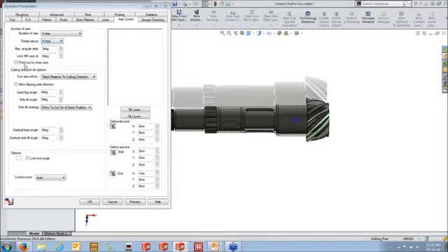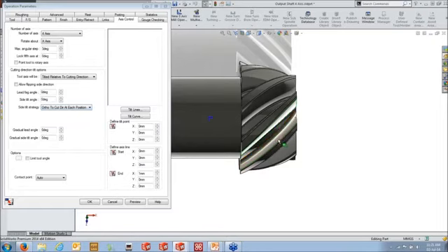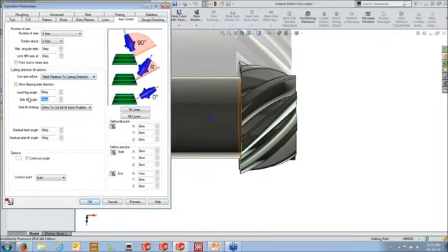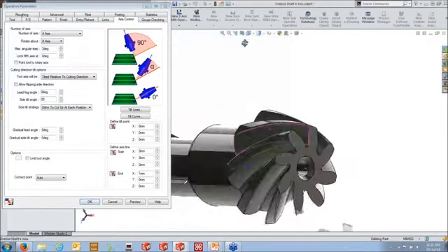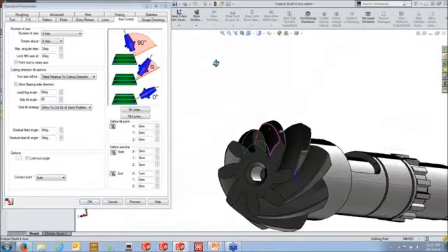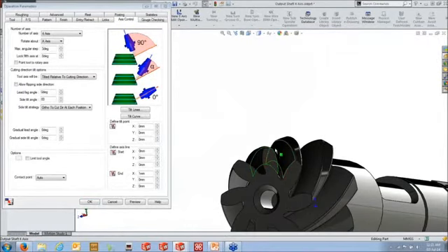And I could check to point it to rotary axis, which would do essentially the same as the rat feature, and point the tool axis always down to that central X-axis. But in this case, because the geometry might be offset a little bit, I'm just going to use some of the side tilt options down here. I'm going to set it to maybe like an 80-degree side tilt. So it's going to actually take the tool, we're just looking at this, say the spindle's coming down here. It's going to be 80 degrees off of the actual surface normal. So that's basically driving it to use the side of the tool to come down here and cut this and swath cut it.